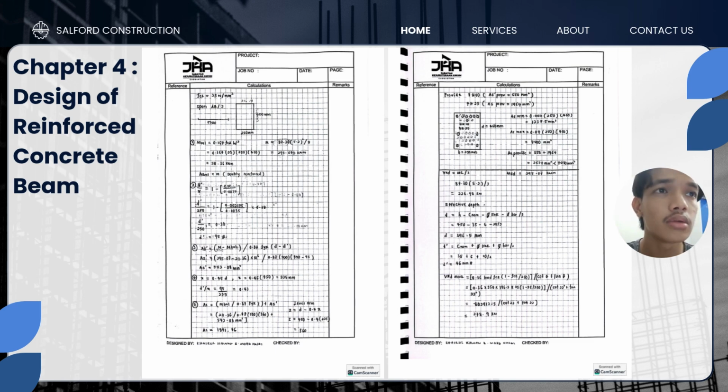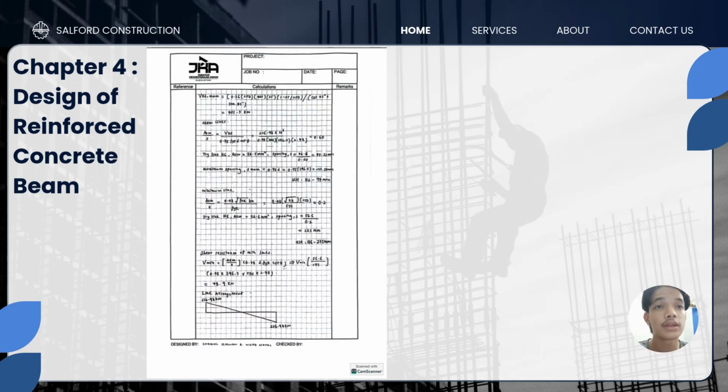So next we're gonna go to the shear resistance. So we need to find the effective depth first, and next we're gonna calculate the concrete strut capacity. Next, for this slide, it was continuing the last calculation. So after we find the concrete strut capacity, we're gonna calculate the shear length and maximum spacing of steel bar.